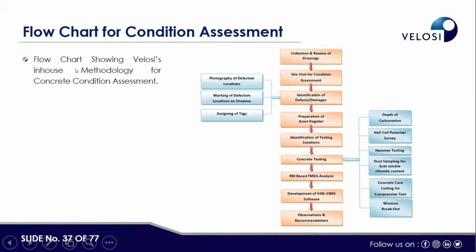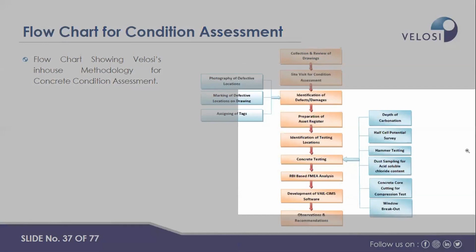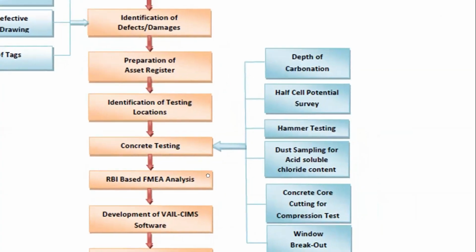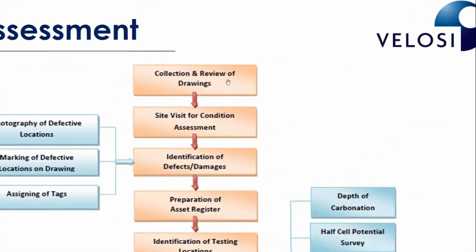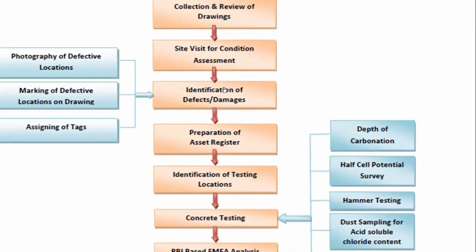So this is a flowchart showing Velosi's in-house methodology for concrete condition assessment, which we use as a modified version based on the above standards. In a way, the approach is the same: collection and review of drawings, site visit for condition assessment, then identification of defects and damages.